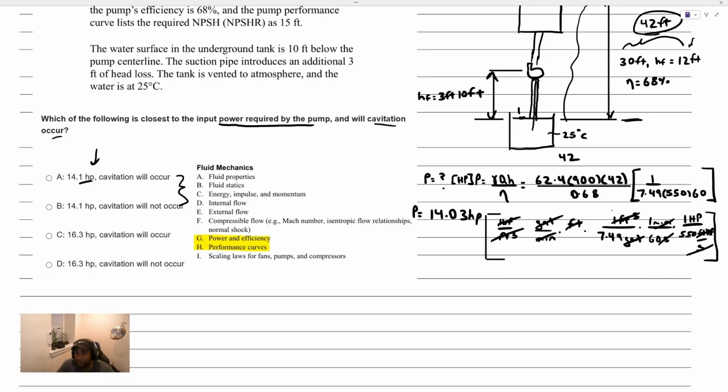If you decrease the pressure by a lot, water can boil at a temperature like 25 degrees Celsius. And that will happen if you drop below the vapor pressure. Cavitation is what's going to occur when, at the entrance of the pump, you go from liquid to vapor. So you have this kind of liquid vapor mixture that's entering your pump, and the pump's job is to increase the pressure of the fluid.